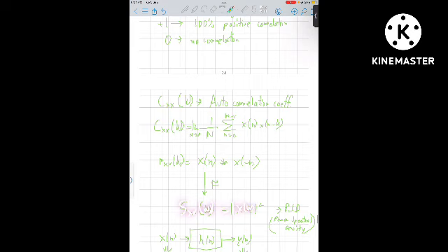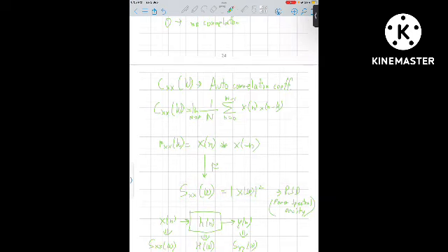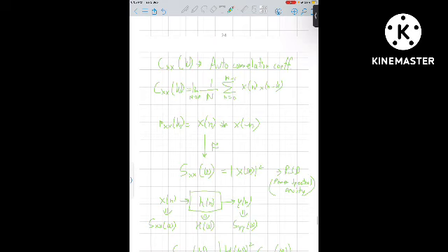I hope that you already know these things because it was a part of the prerequisite. And this filter has a Fourier domain representation H(omega). If we want to find the power spectral density of our output, how do you obtain it? S_yy(omega) is mod of H(omega) whole square times S_xx(omega). Okay. So is the correlation coefficient and the basics behind it clear to everyone?